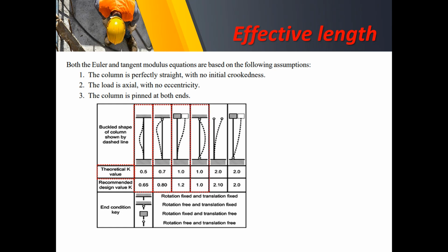We also have the hinge-to-hinge connection on both ends, and the fixed to a free end, wherein the free end is free to displace horizontally and rotation is allowed. And we have also the pin at one end and a roller which allows horizontal displacement.